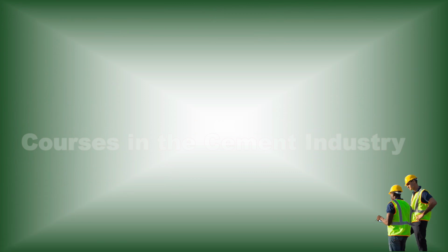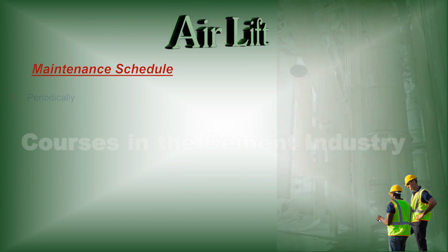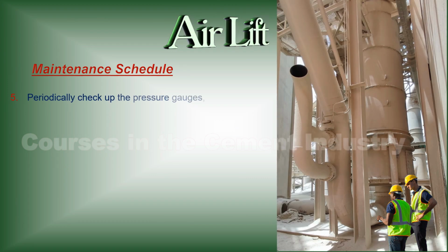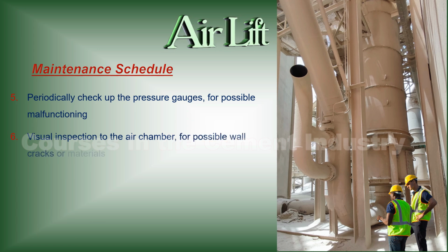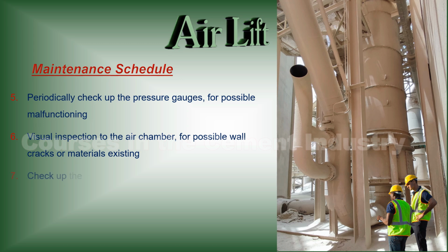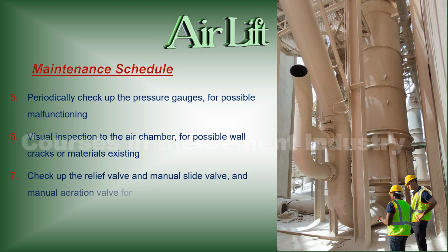We follow together the maintenance schedule for airlift. 5. Periodically check the pressure gauges for possible malfunctioning. 6. Visual inspection of the air chamber for possible wall cracks or material buildup. 7. Check the relief valve, manual slide valve, and manual aeration valve for possible internal damage.